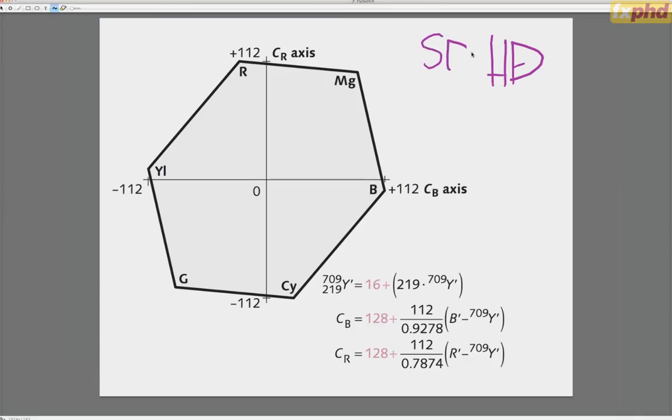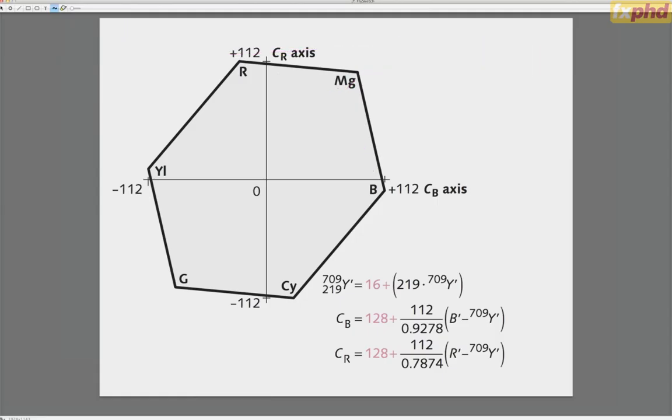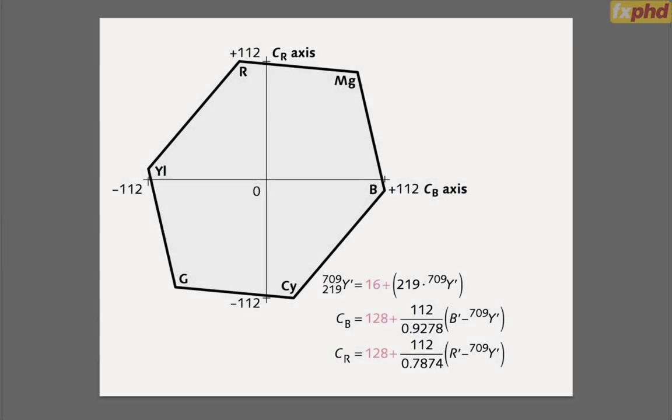So you have to know that there's SD and HD flavors of YCbCr, even though there's only one flavor of RGB. So there's two different coding systems, one for SD, one for HD. And you can tell if you glance at a vector scope because the vector scope looks different. You know, magenta's way out here on the HD instead of being kind of here for the SD. So sad but true, live and learn. You just have to put up with it.